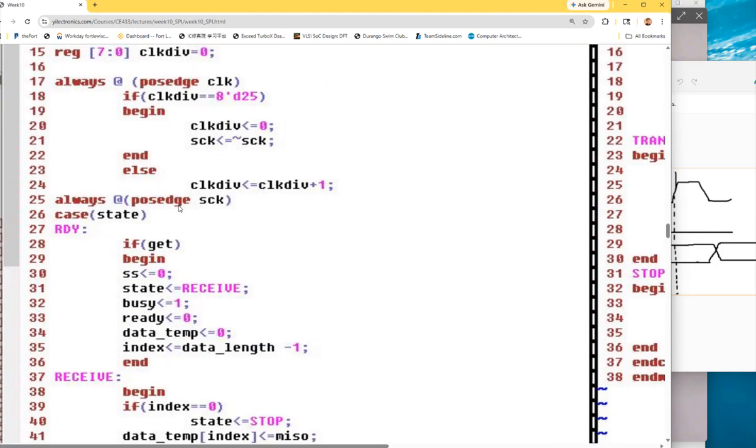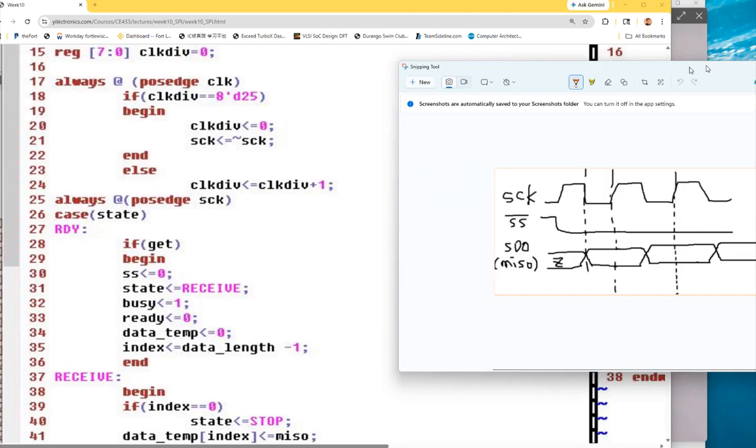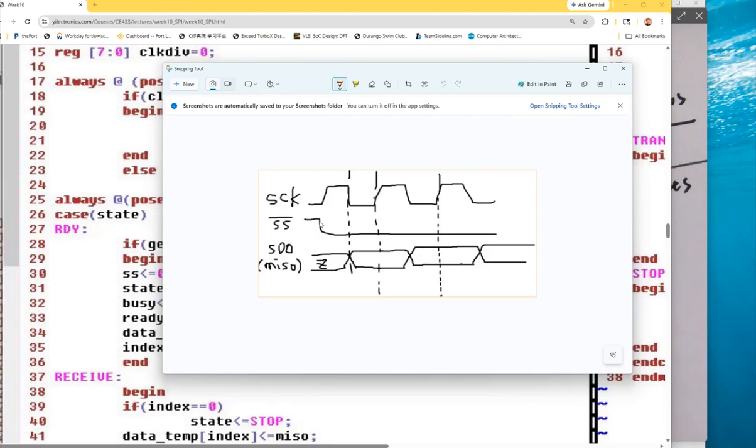So remember the rising edge of that CK, exactly the first one, right? The first rising edge of that CK will do what? It will enable it. So the first rising edge of that CK enables it, but does it do anything else? No, the data is not available yet. So you're getting high impedance. So Z, high impedance, nothing.